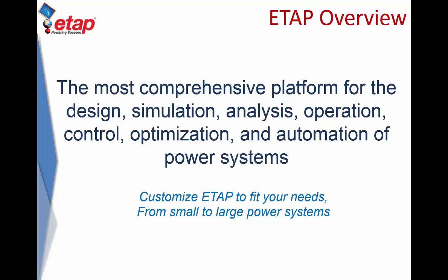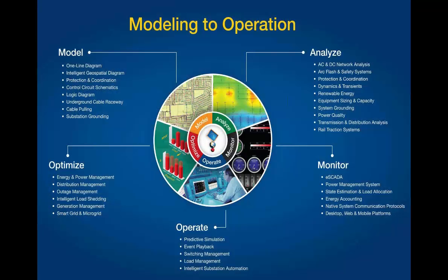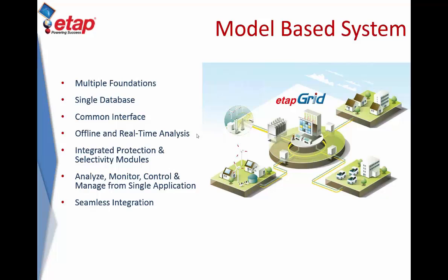ETAP is essentially a platform for design analysis as well as operation, control, and automation of power systems. So essentially with ETAP you can go through the entire life cycle from modeling to analysis into monitoring, operations such as predictive simulation and optimization. The program essentially utilizes a single database with multiple foundations or multiple views, and it's able to utilize offline and real-time analysis information. It includes protection and selectivity modules, and because it's an open platform, it allows for seamless integration